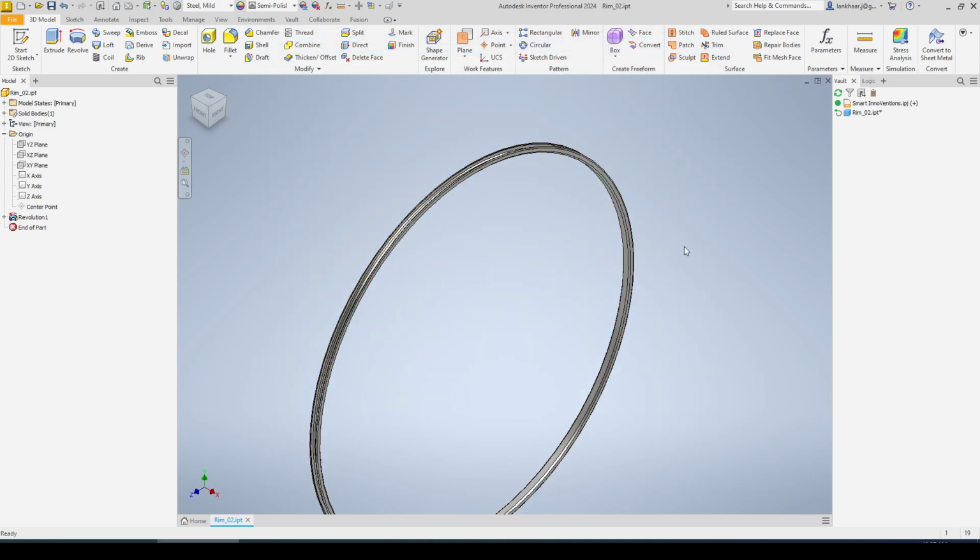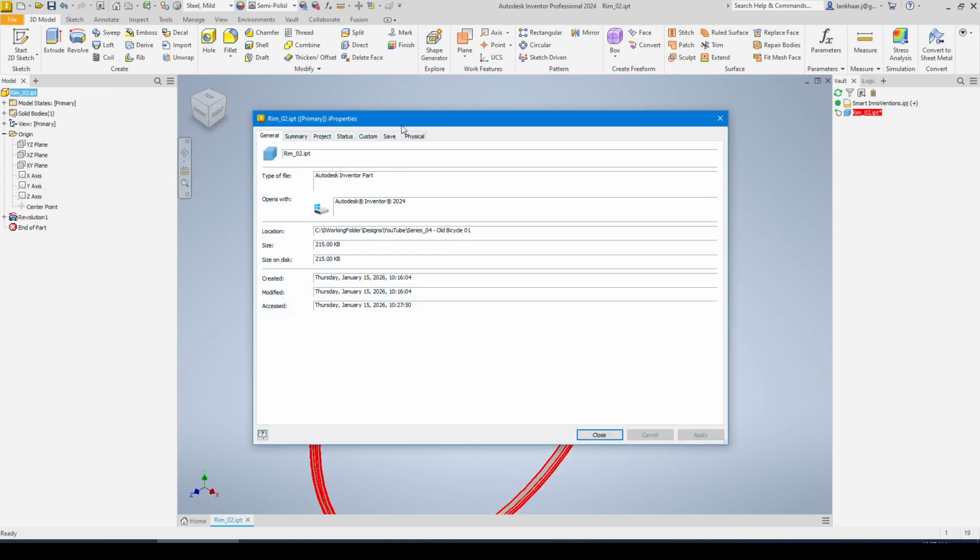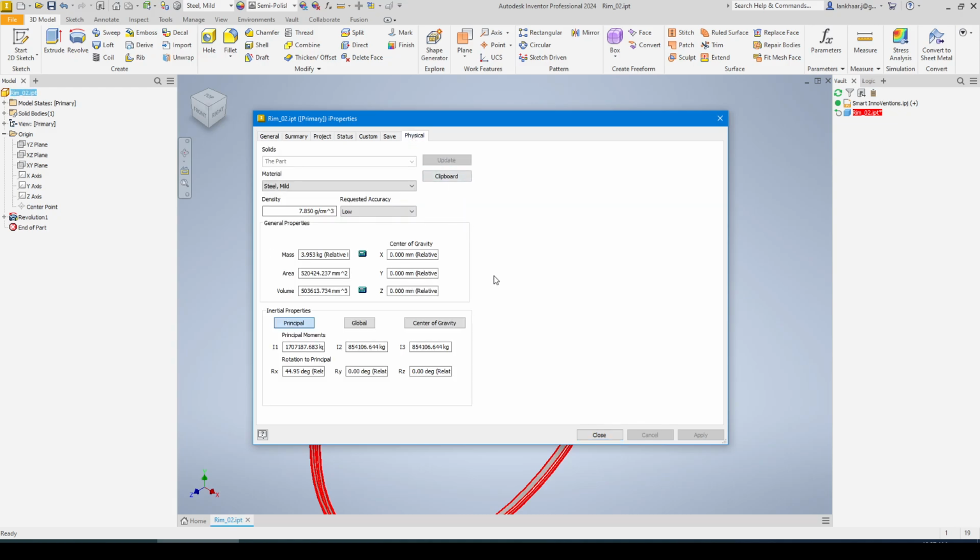And why I like CAD systems like SolidWorks, also Solid Edge, and also Inventor: these CAD systems use solids, and with a solid you can add material, and it really gives the right weight also. Let's try, because there is a way to figure that out. Properties, physical, update. This thing will weigh almost 4 kilo. And if you change the units, you get it in pounds and everything. So I use the metric system. 4 kilo will be around 8.5, maybe 9 pounds, something like that.